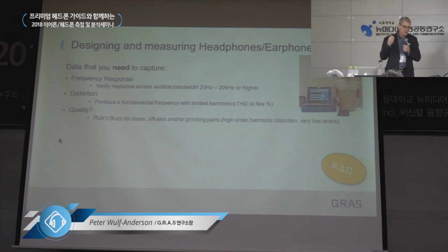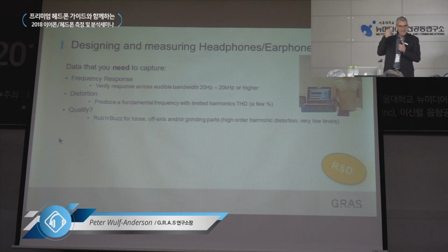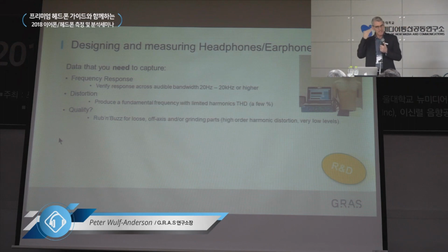Also, you need to do tests for any little defects in the driver in your headphone, the rub and buzz, where you test for loose particles or grinding parts inside the driver. And again, these can be noises that are far away from the fundamental, meaning the actual tone creating the noise, and therefore can be very easy to detect by the ear.